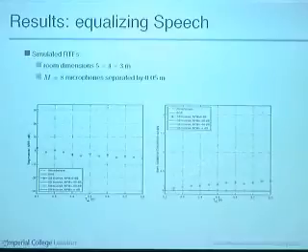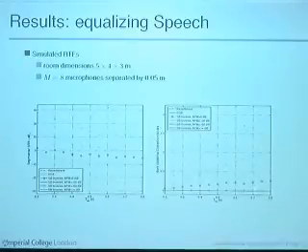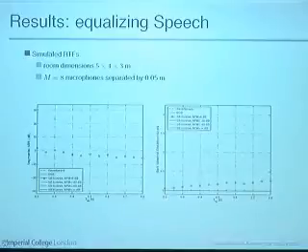And a similar thing you can get in terms of bark spectral distortion. Again, here is the unprocessed signal. This is a beamformer, and down here are all the lines for the equalized signals. So in this case, we can say that bark spectral distortion is more sensitive to small improvements, while the segmental signal to reverberation ratio shows us when you have higher improvements, at least as an indicator of what we're doing. Because practically yours are down there.